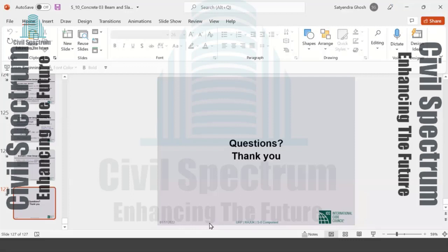And even when you do not have a deep beam by the definition of deep beam, we have something called skin reinforcement. I think it came up when I was doing the flexural module. Remember skin reinforcement? I think that starts at beams exceeding 900 millimeters in depth.